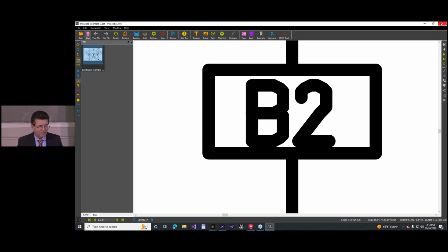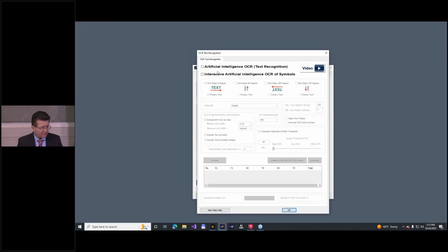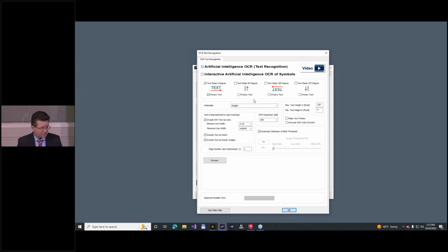But you can help here with one parameter. I show this parameter. If you go here again to the artificial intelligence function, okay, you can define that we have only horizontal text. Text is English, United States, and my text is only as a line, you see. But the minimum line width is 1.8 and the maximum line width is line weight 2.